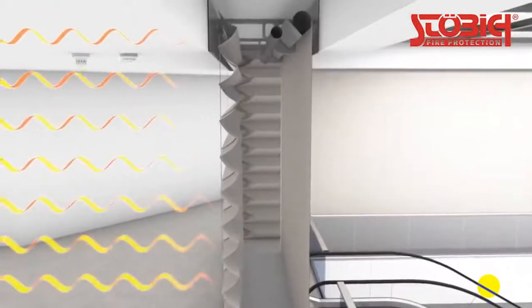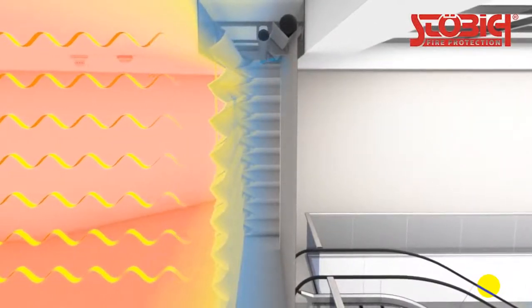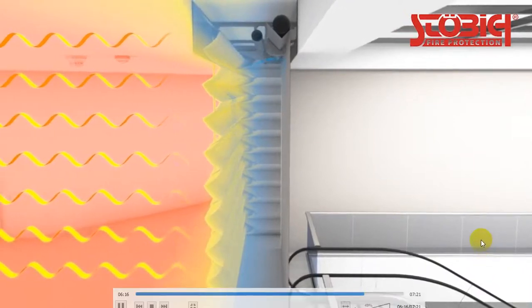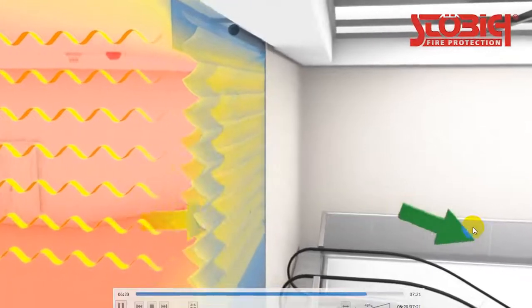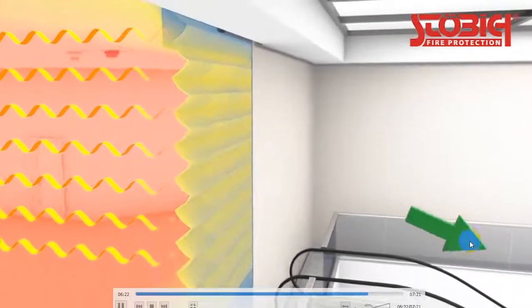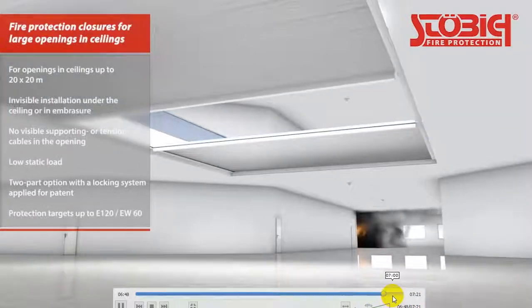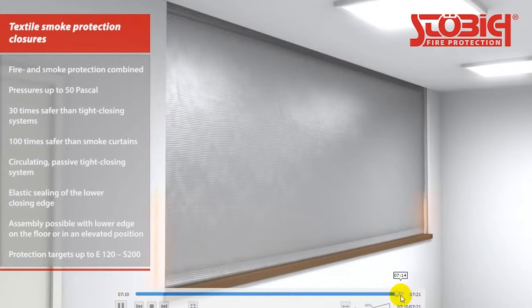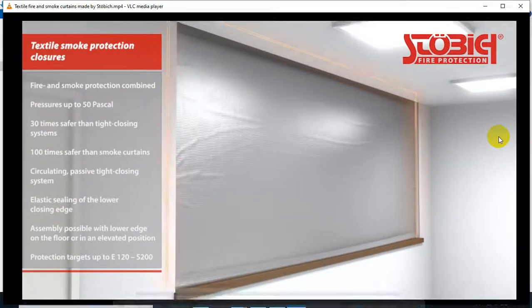The outermost side of the system includes fabric that folds out, just like a standard system. The inner side of the system has a second fabric that unrolls from a tube. If cooling is necessary, sprinklers can be placed in the space between the two fabrics. Optionally, the system can even be equipped with one or more escape floors. Considerably higher requirements regarding perimeter edge sealing and special fabrics make it possible to protect against both fire and smoke at the same time.